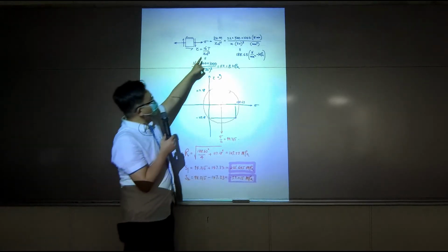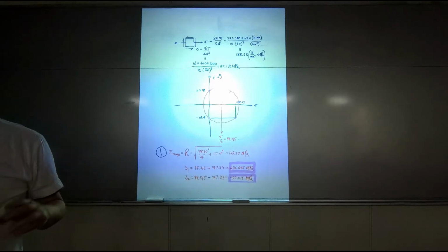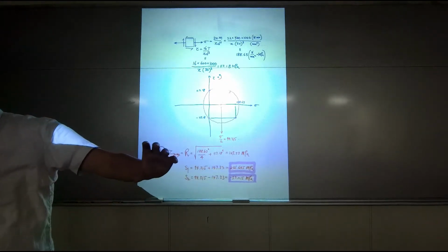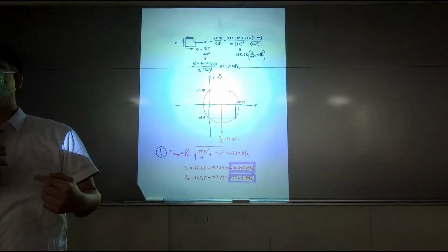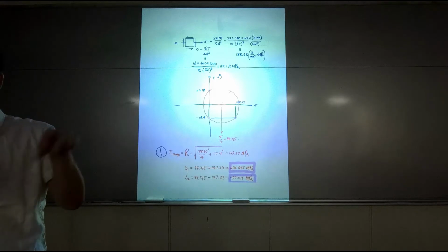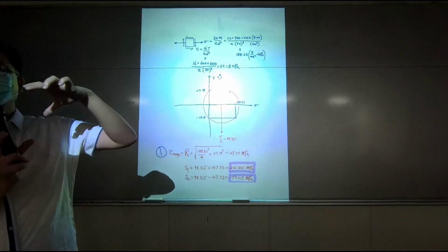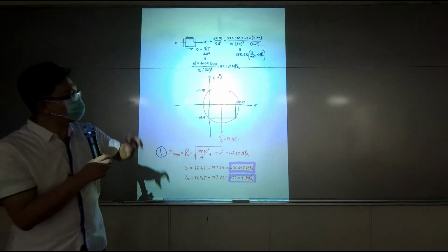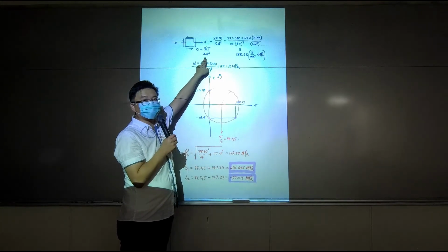We have this equation only because we determined the area moment of inertia of a shaft. So the cross section is a circle. We calculate I and J. For the circular area, I and J can be derived, and we use them to get those equations at the end.